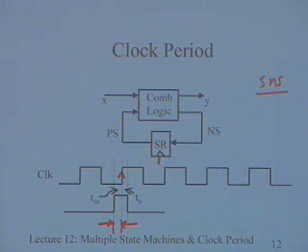See, basically, all these digital phenomena are only a simplification of the analog processes going on in the flip-flops. All circuits, all real life, is essentially analog, not digital. There are capacitors, there are resistances, they are charging. So it does take some time for the charging to take place when going from 0 to 1, or for the discharging to happen when going from 1 to 0.